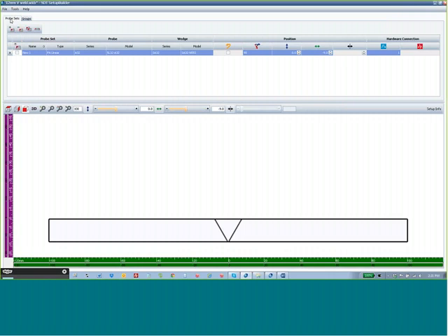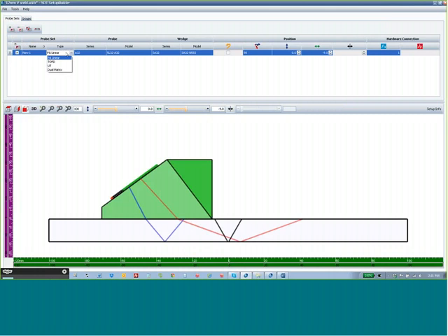We'll go to the Probe Set tab and add our PA linear array probe. Again, a new functionality that you'll see in this version is support for dual matrix arrays for austenitic inspections. We have an upcoming webinar similar to this one on use of those probes as well. The probe we're selecting is from our new weld series probes. The A32, A11, A2, A12 probes work very well with the same inspection strategy.